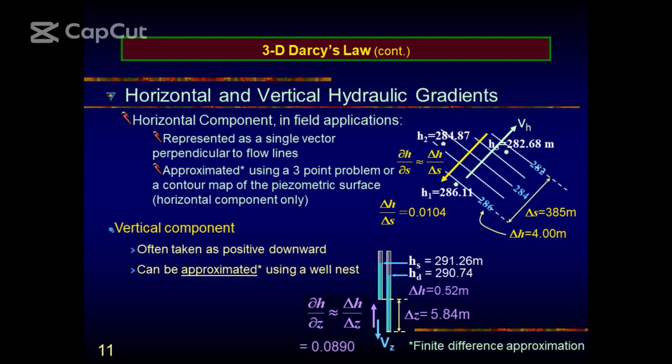If it is open at the top, the water will reach the level of the water table. Why? Because it's not under pressure. When you have a bowl, a bucket, and then a tube, it may even rise above due to capillary action, depending on the size. If the tube is so small, you have capillary rise. If it is so big, then at minimum the water will be at the same level as the water in the bowl. So why do we have a different case here?